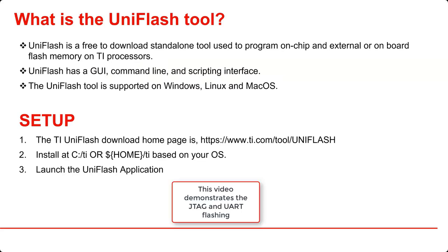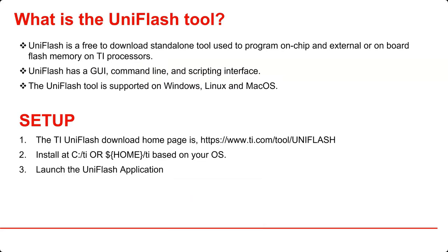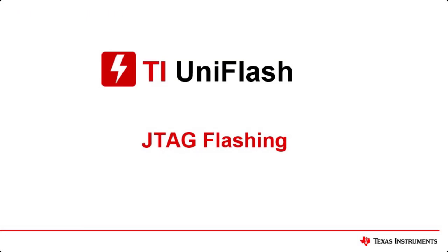For this video, we will be demonstrating the JTAG and UART flashing on the AM263PX control card. We will be using MCU Plus SDK for AM263PX version 9.2. The Uniflash tool supports JTAG, UART, and custom flashing.